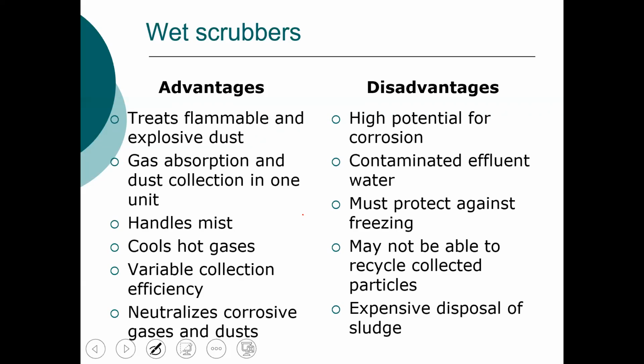So you have to address the potential impact of corrosion. The other major problem is that you're simply transferring your contaminants from the gas stream to a water. So you start with contaminated gas, you end up with contaminated water, and then you need to treat that contaminated water. Depending on how large this unit is, where it is operated, freezing can be a significant issue.